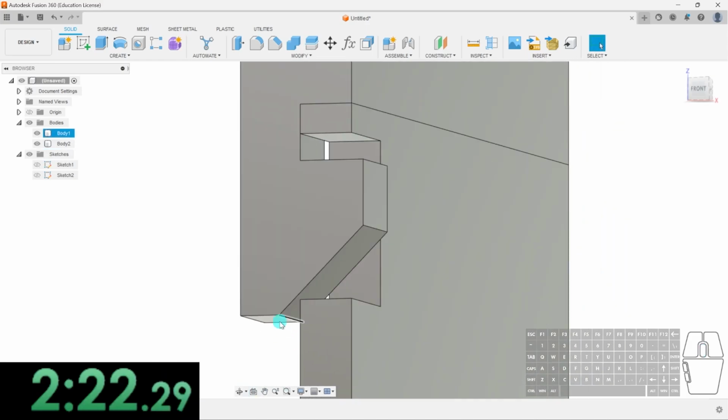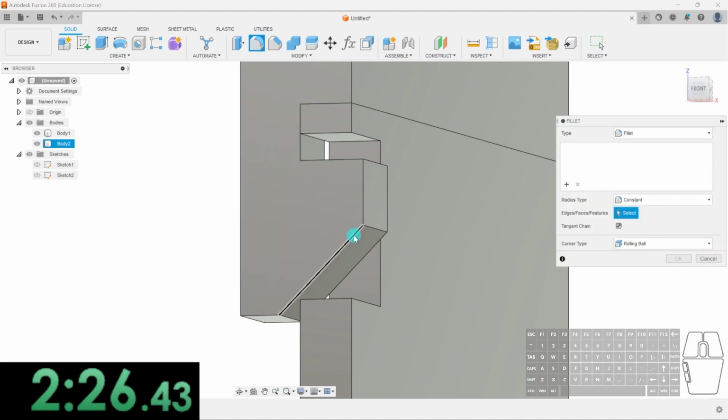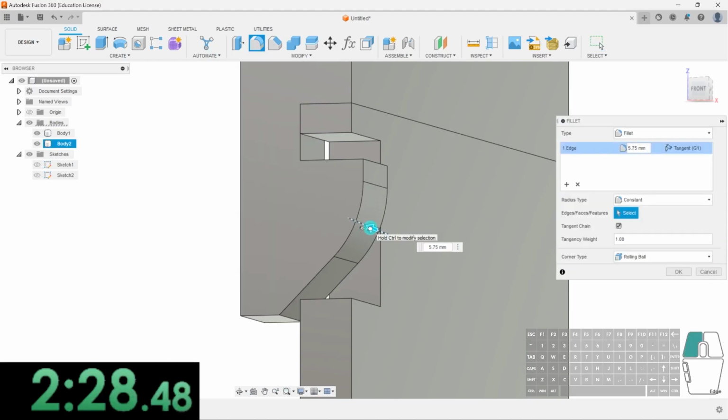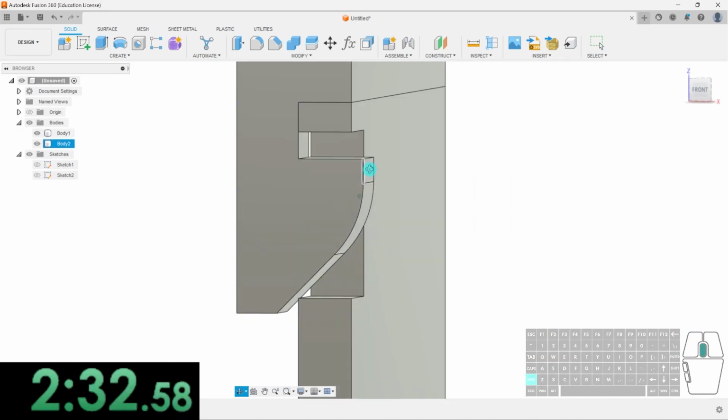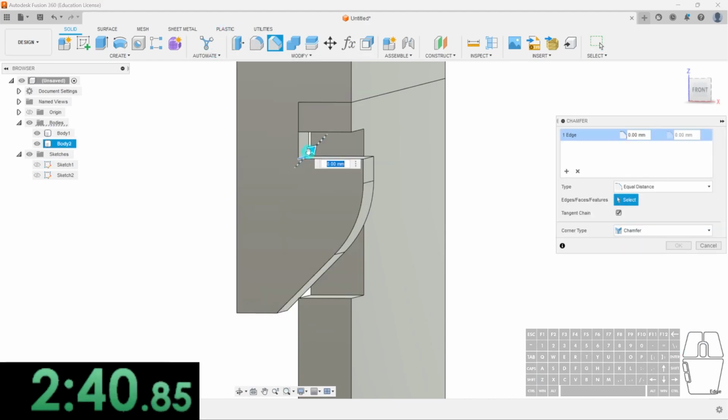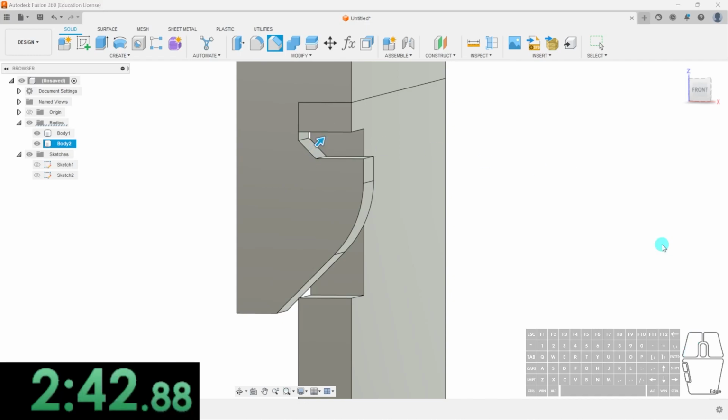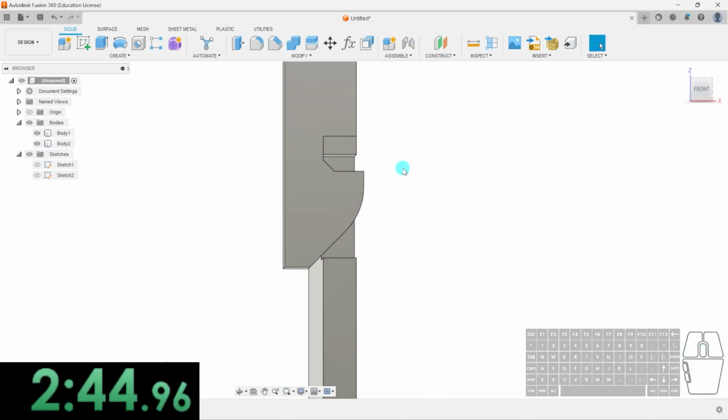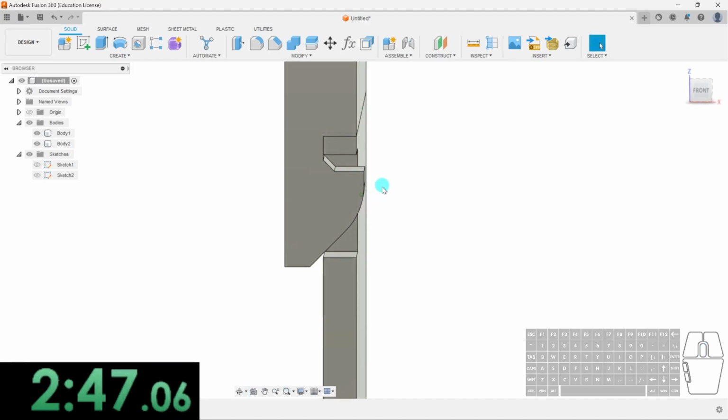And I can think, okay, how would I want this to snap in? Maybe I want it to be a little bit easier, less of a snap. I can always fillet this edge and make this a bit smoother when I'm slotting it through, right? I don't want to scratch my box or break it. Similarly, I can always make it a little bit easier to remove by adding a chamfer here on this side. However I want. Again, play around with the design. There's a design manual, look online, see what kinds you have.